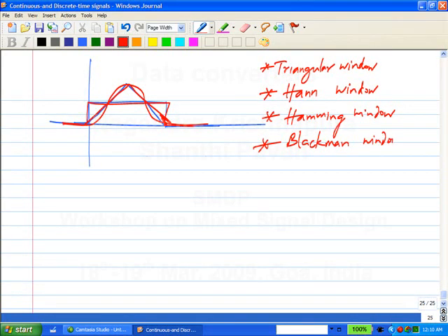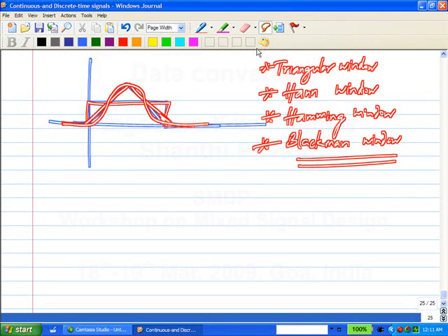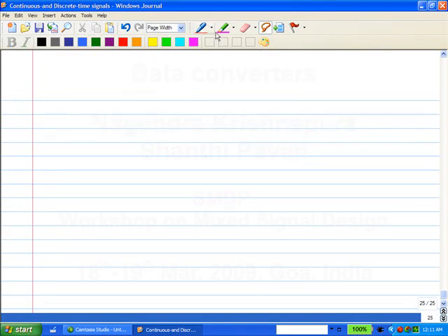Now there is not enough time to go through the actual Fourier transform for all of these. I'll just briefly discuss the Hann window, which is a very good window in that for most general cases it reduces the leakage to acceptable levels, and certainly in our delta sigma work we use the Hann window whenever we are simulating. Now it will have some other effects which I will also discuss but not derive. I will just tell you what it is. So there are lots of windows, and the philosophy is to get smoother boundaries.